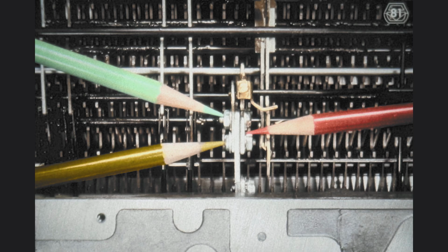Third, we loosen the nut indicated by the yellow pencil, which holds that screw in place. Now we are able to adjust the position of the cycle bail up stop, at the red pencil. This also changes the rest position of the cycle clutch latch pawl, and thereby adjusts the cycle clutch latch pawl bite. While we tighten the screw and the nuts, we must make sure that we do not inadvertently loosen the screw indicated by the green pencil, or we will lose the adjustment of the character interrupter support plate.